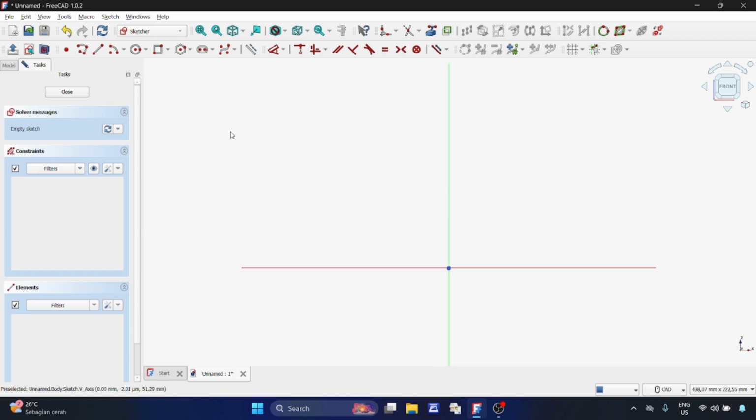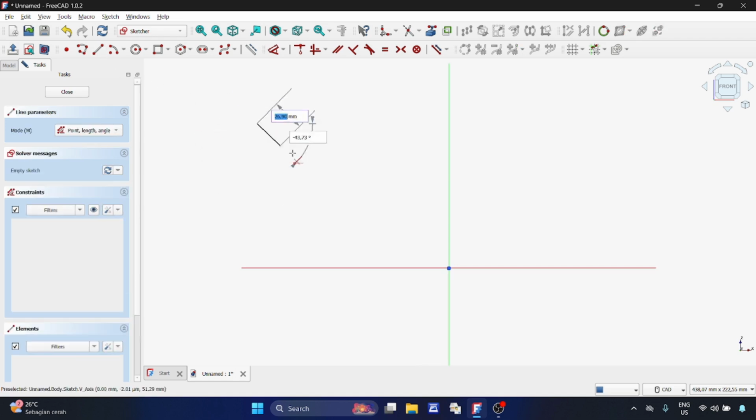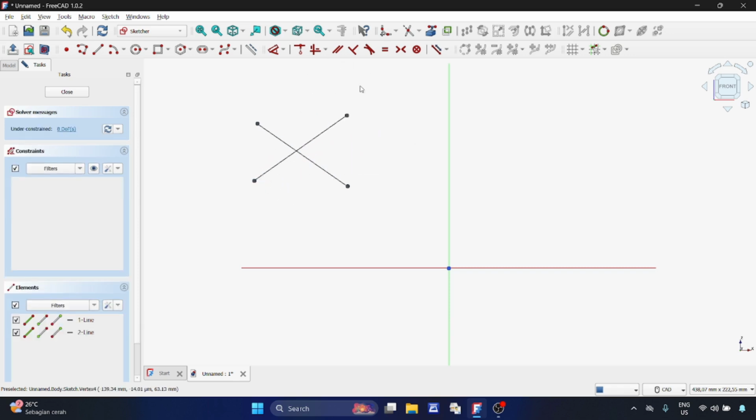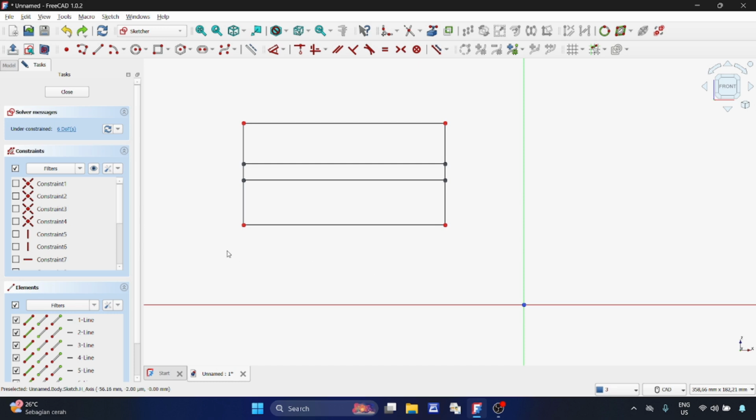The most basic example, two intersecting lines. Let's say I have two lines that cross like an X. I want this end piece to be gone. Watch what happens when I hover the scissor cursor over the part of the line I want to remove. FreeCAD visually shows you the segment that will be cut. It usually changes color. This is super helpful. Just click, and yes! That segment is instantly trimmed back to the intersection point. Simple, right?